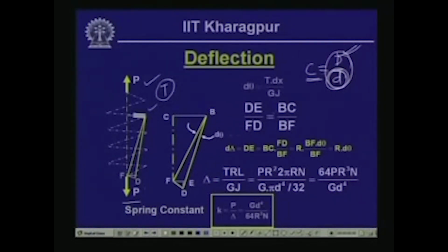or for springs having a larger spring index, if we consider a small element in the spring, let us call this distance AB. Virtually this becomes like a straight length, that means you have a straight rod which is subjected to a twisting moment, and in this particular case we ignore the effect of the axial or direct shear, the deflection that will be produced by the direct shear. We will be evaluating the deflection that will be caused by the twisting moment T.